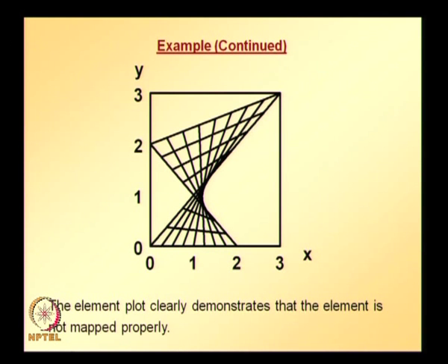And now let us look at numerical integration for quadrilateral elements, because the matrices and vectors that we are going to get for quadrilateral elements, the integrand for the integrals is not going to be a constant like in the 3 node triangular element, which is linear, but they are going to be functions of x and y, or in turn functions of s and t.